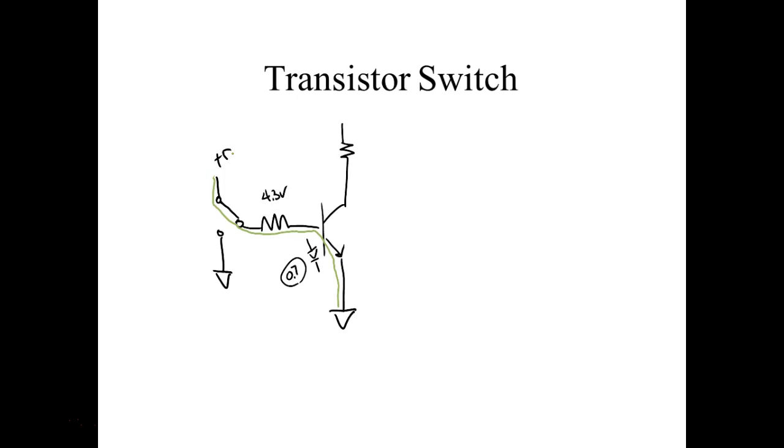Okay. So we have to size a resistor to drop 4.3 volts. 0.7 would be for the P-N junction that's between here. So that's a P-N, we call that a P-N junction. So that's basically a diode. Everybody okay? Are we okay? So then, it's just a series circuit, guys.